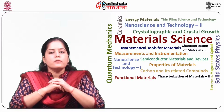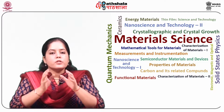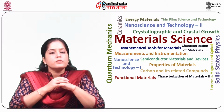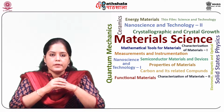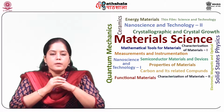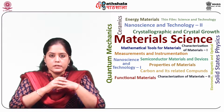This is derived from low field conductivity, while the average time between collisions in which energy is lost, that is the energy relaxation time, is about 1 picosecond in gallium arsenide. So the effective time for transfer between valleys is estimated to be 1.5 picosecond, as reported by Cromer in 1978.